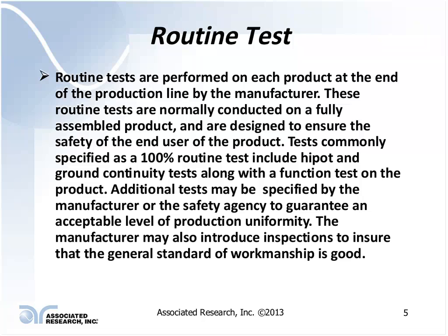Some of the routine safety tests that are done on the product itself, typically if the product is designed to have a grounded enclosure, a Class 1 product, where it is relying on a grounded chassis or grounded metal enclosure to provide the second line of defense to guard against an electrical shock. The first line of defense, of course, is the insulation within the product itself. The second line of defense is this grounded enclosure.